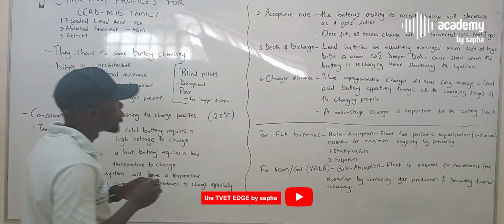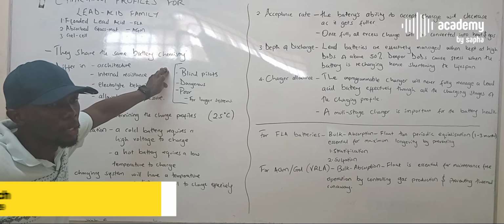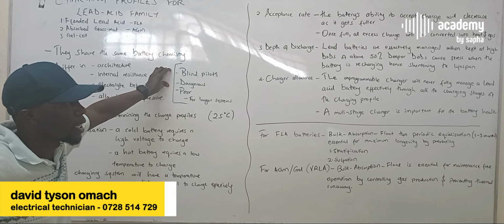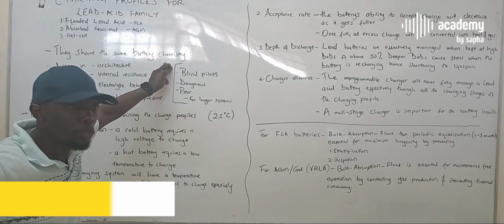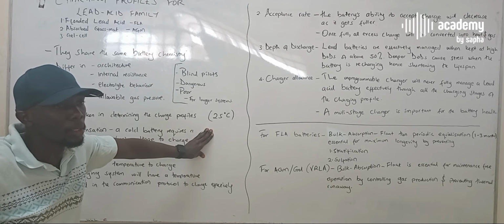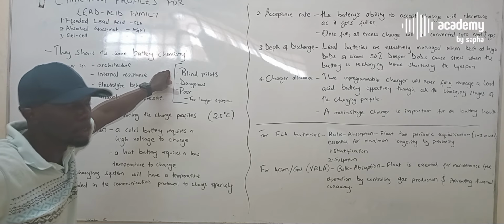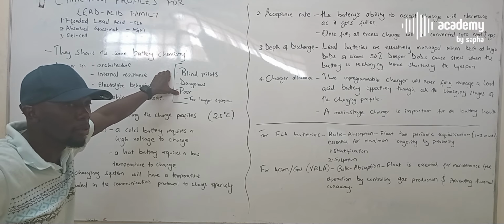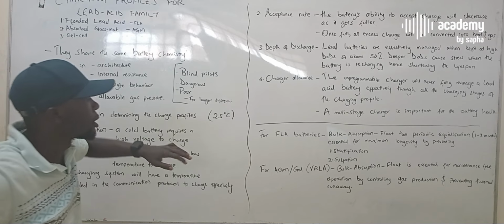These are the charge controllers that do not come with any form of programs in them. They just basically have electronics that allow them to filter the voltage coming from the panels and release the required amount into the batteries. These ones are dangerous for bigger systems and reduce the lifespan of the system by far.